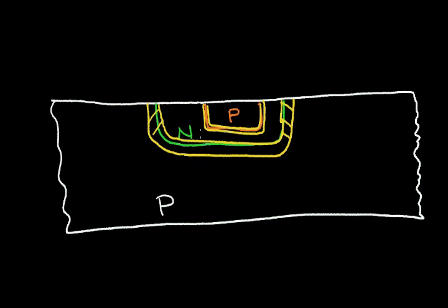Now I can just look at this wafer, this silicon structure, and I know that this p region is lightly doped, and this n region that I added has to have a higher concentration of dopants, and this p region that I finally add in must be the highest concentration of all. So I can look at this and I can know that this depletion region between this n and p region is wider. And it's wider because the concentrations are lower.